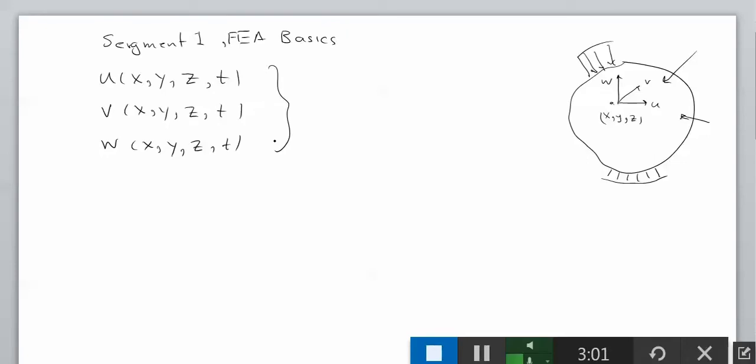Our interest may be in the displacement, but there is an underlying reason for doing that. Because once you have the displacements, the displacements will lead to strains, which can be calculated, and the strains, using material properties that you know, will lead into stresses. Probably stresses are one of the ultimate things that we want as a mechanical engineer. If the stresses are too high, keep in mind about what I said about large stress. You have to be careful about the statement that I'm going to make. If the stresses are too high, the material may fail, and that may not be desirable.